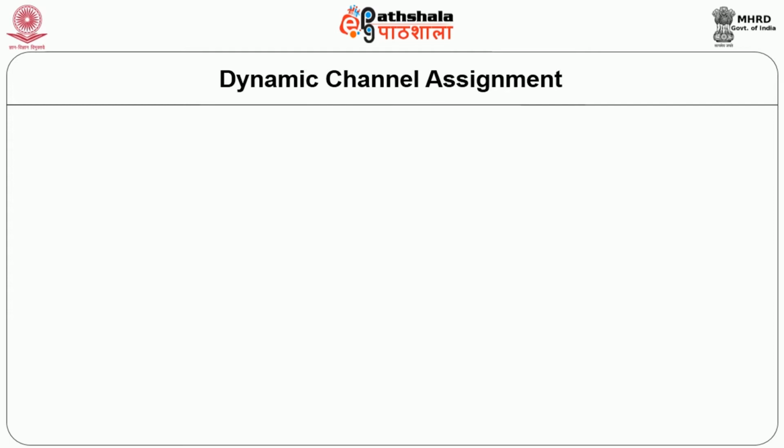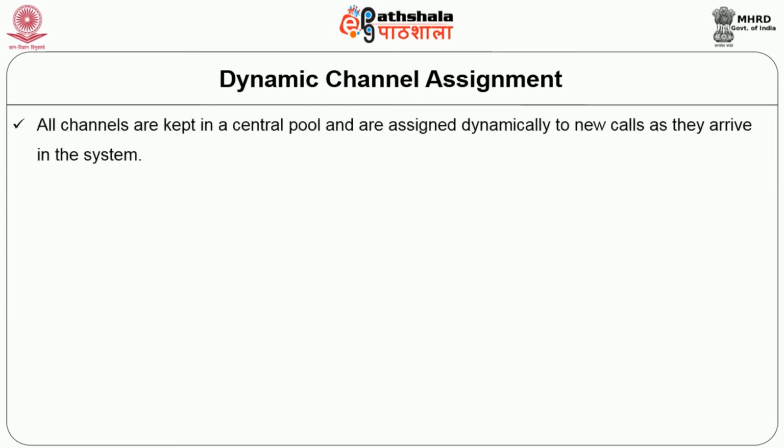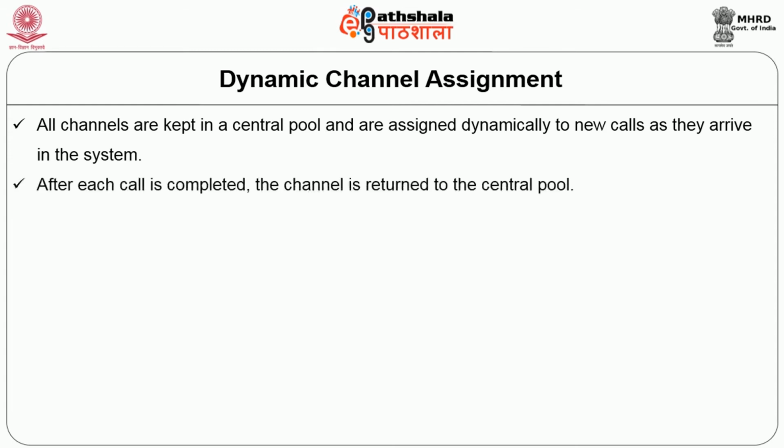The next scheme is dynamic channel allocation. In dynamic channel allocation, all the channels are kept in a central pool and are assigned dynamically to new calls as they arrive in the system. And after each call is completed, the channel is returned to the central pool. It is fairly straightforward to select the most appropriate channel for any call based simply on the current allocation and current traffic, with the aim of minimizing the interference.